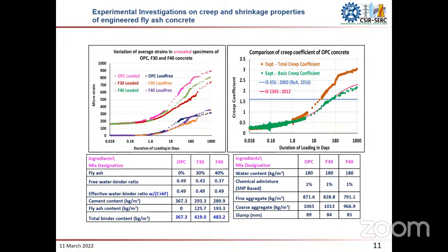So in the case of prestressed concrete bridges, more creep happening means more strain and more prestress loss, as the length of the beam is shortening. That prestress loss leads to deflections. Once it is deflected, cracks will appear. Obviously it will be exposed to the chloride environment, and spalling will occur. These are the typical scenarios in many national highway bridges.